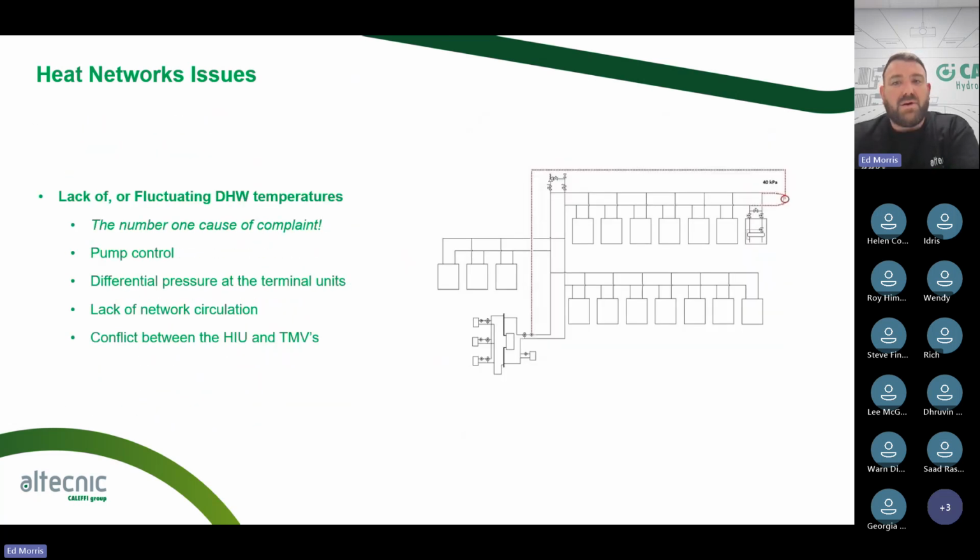Okay, so we can see here this is the most remote part of the system. This is the furthest point. If we were to put an index sensor here, you can see my mouse, so this is the most remote part of the system. Can you see my mouse on that screen? The index sensor we've put here is the most remote part. If we were to install it here, there's still a lot of pipework to run up here to see what it can do. If we put it here, it's not the most remote part, because the water's lazy: it will circulate around here and not necessarily push itself up here. So we would always recommend it at the furthest point.